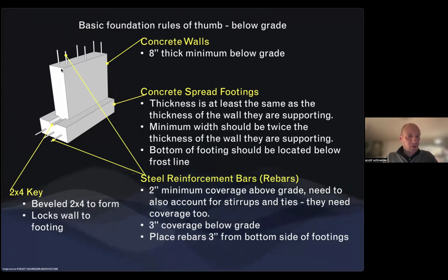And then in terms of rebar, when you're above grade, you have to maintain 2 inches of coverage, which means the rebar needs to be at least 2 inches from the face of the concrete. When you're below grade, that is 3 inches of coverage.